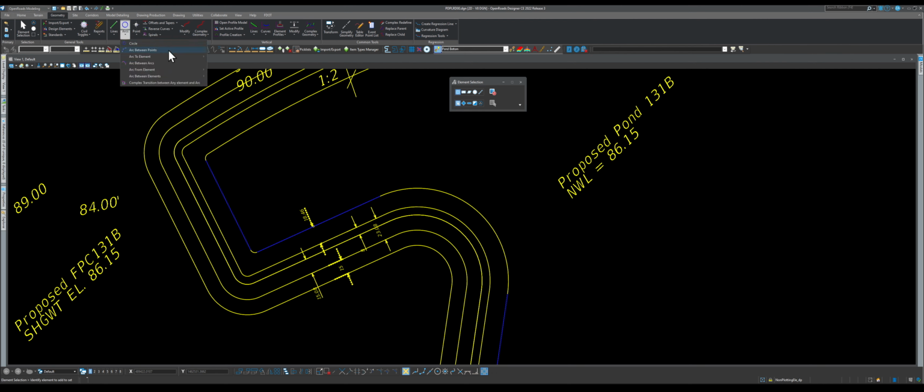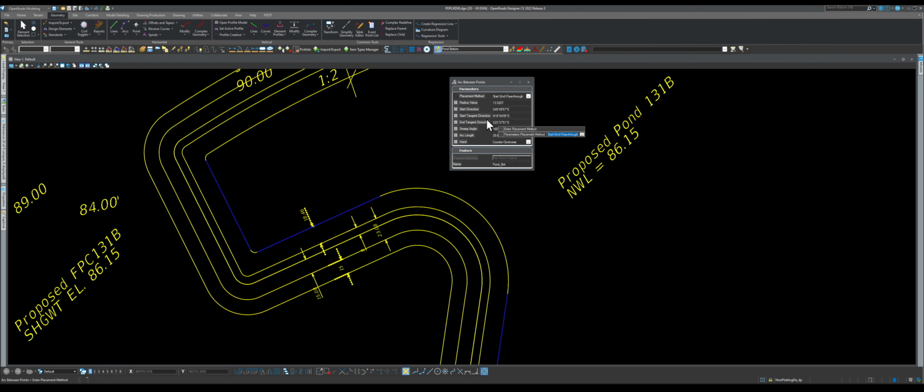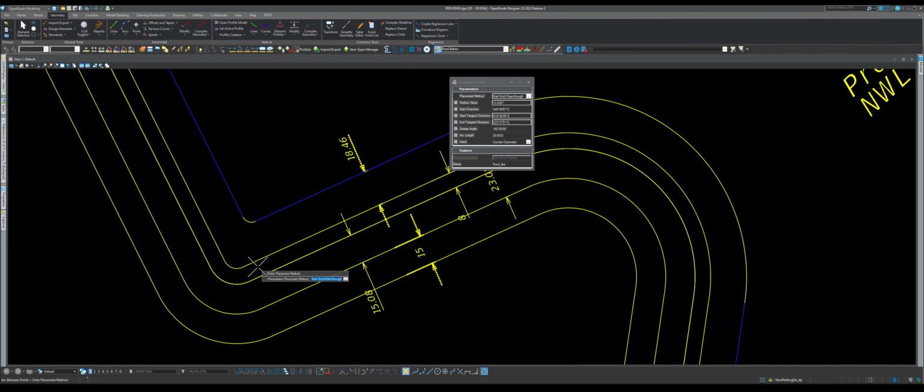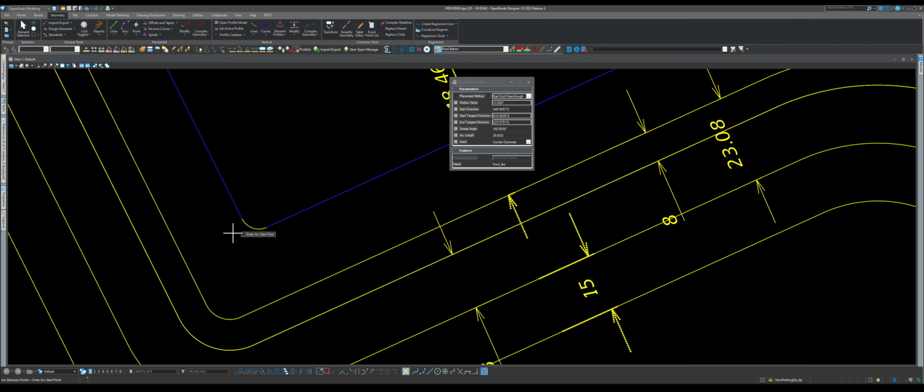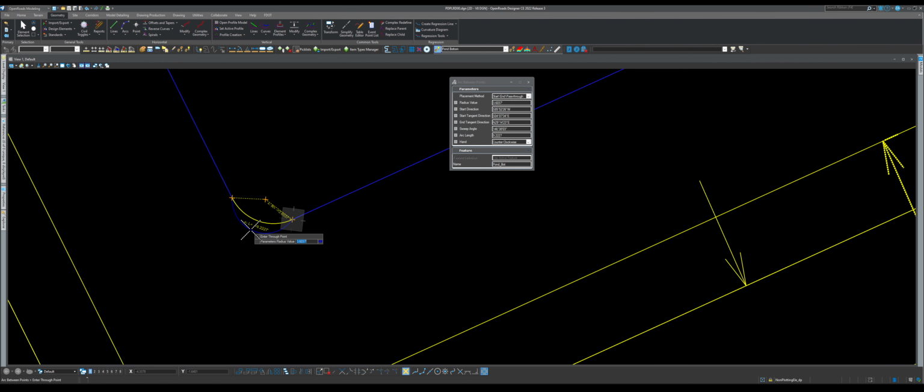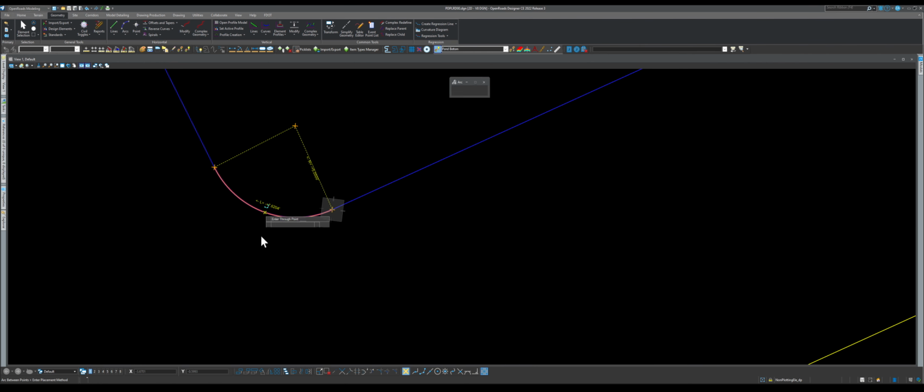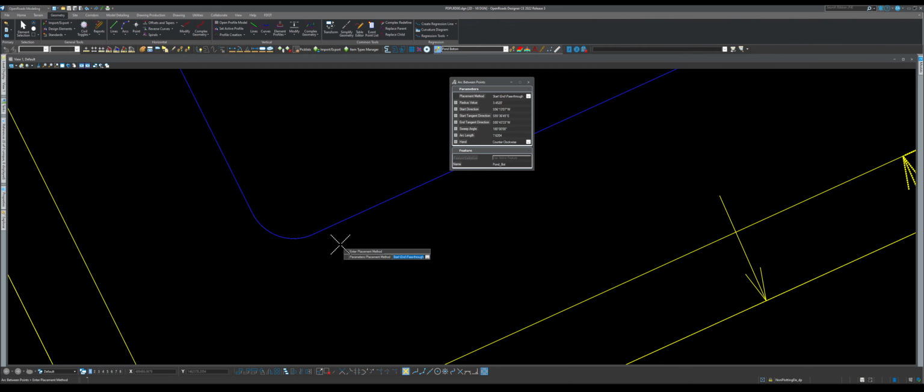So an arc between points is the same one as the 2D one. It's called start and end and pass through. That's the one that I like, which is you click one time to activate it, and like I said before in RD 101, pay attention to the tools here, because it usually tells you in the bottom what you need to do. So it's telling me to select the start point, so that's the start point, and then I have the end point, right? And then I need to do the pass-through, or the center, just click it here. Because I already know this, and I already have a guide, I'm doing it.